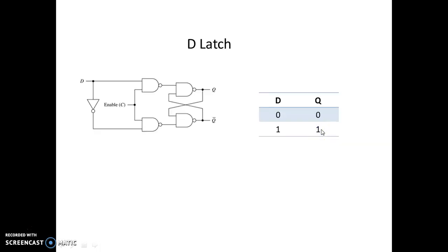The next application is the D latch. It is the extension of the SR flip-flop where the S and R inputs are short circuited with the help of a NOT gate, so that whenever one input is 1 high, the other automatically becomes low, and when one input is low, the other becomes high. Hence only the two states 0 and 1 exist.